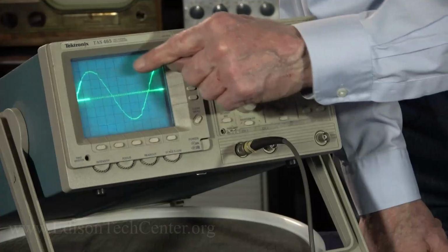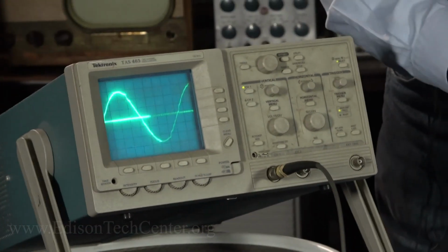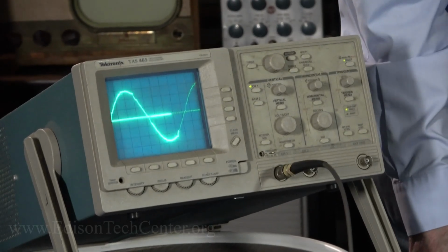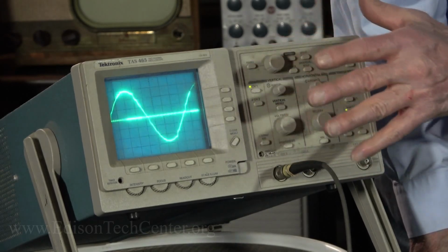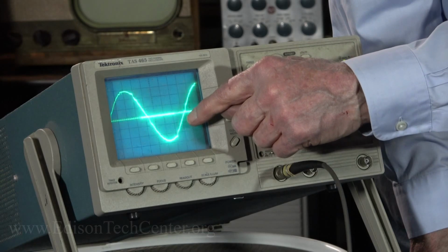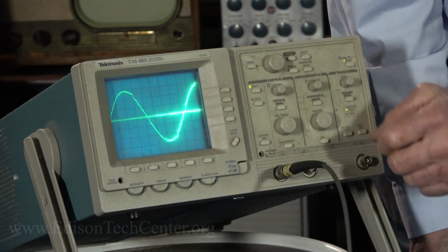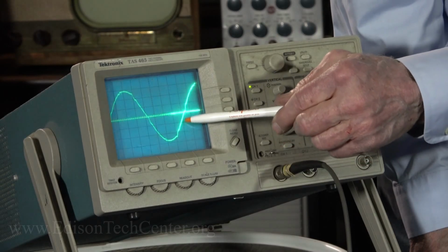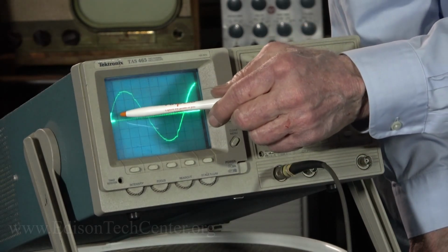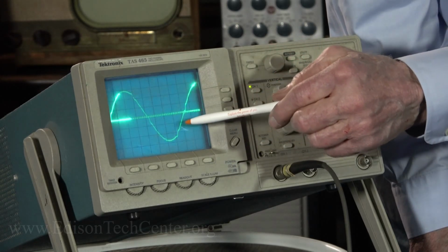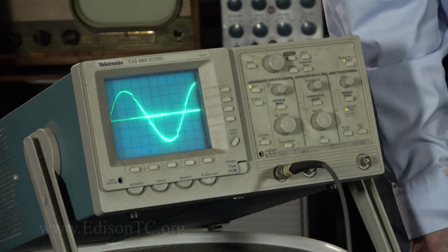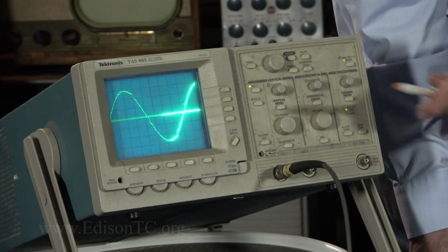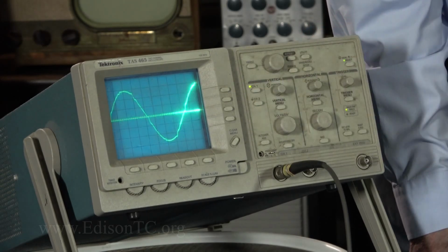And you can see all these little wrinkles are primarily due to other pieces of electronic equipment that are putting harmonics onto the waveform. And this is a digital oscilloscope, so you can actually take the value of each of these little wrinkles and see what the time variation is from the start to where you get one of these, and also the amplitude of it. And then you can go back and see where in your system